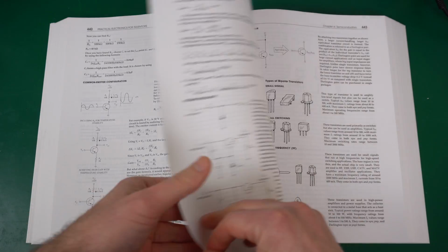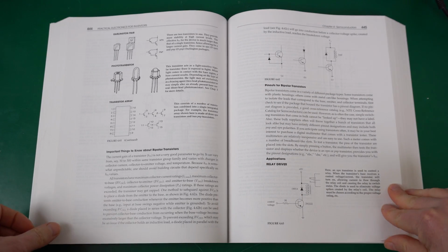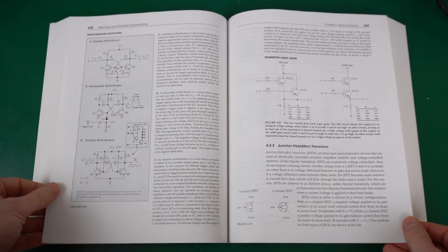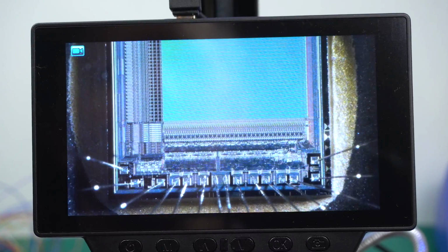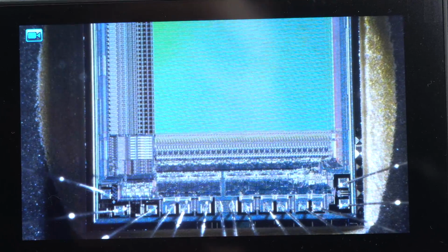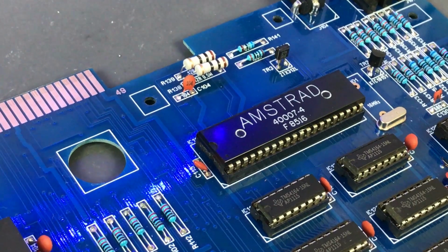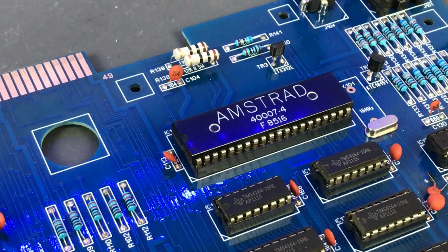So unless you're getting an exact replacement with all of the same parameters, the safest approach is to look at the circuit where it's being used and try to understand its exact role in there. That's because transistors are used for all sorts of things, to act as switches, to amplify signals, to stabilize current flow, to turn signals into digital signals, or to perform all sorts of operations on them, especially once you combine transistors together. A lot of the transistor magic is already happening inside each integrated circuit, so we don't usually have to think too much about this, and instead we can focus on the high-level behavior of the chip itself. But when transistors are loose in the board like that, then we really need to pause a moment and make sure that we understand them.